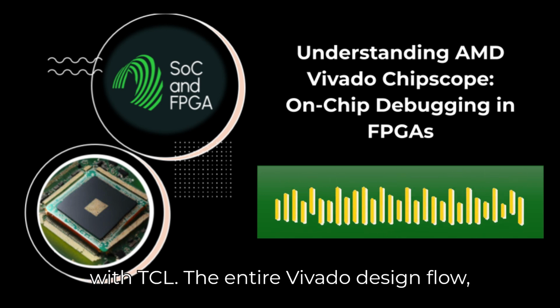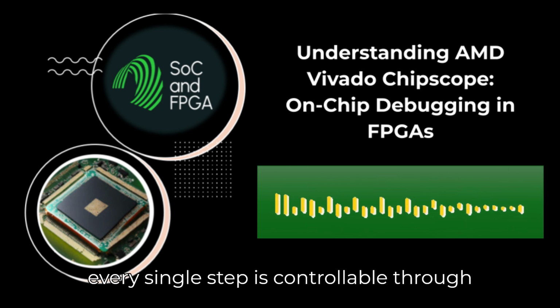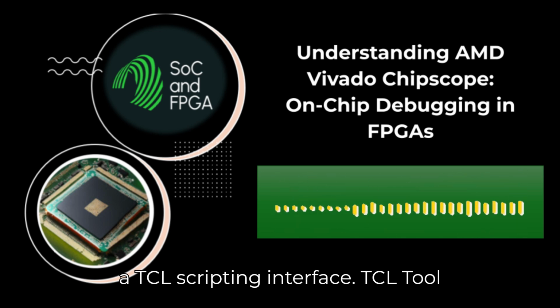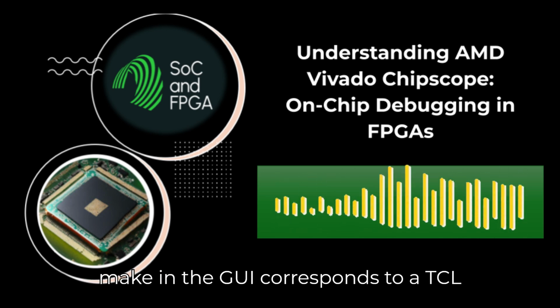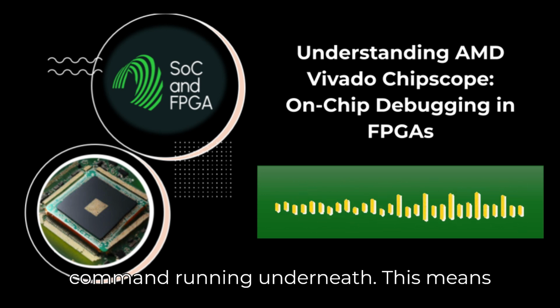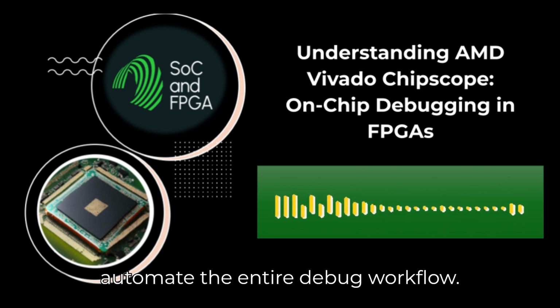Scripting and automation with TCL. The entire Vivado design flow, every single step, is controllable through a TCL scripting interface. TCL, tool command language. Yep. Every click you make in the GUI corresponds to a TCL command running underneath. This means you can write powerful scripts to automate the entire debug workflow.